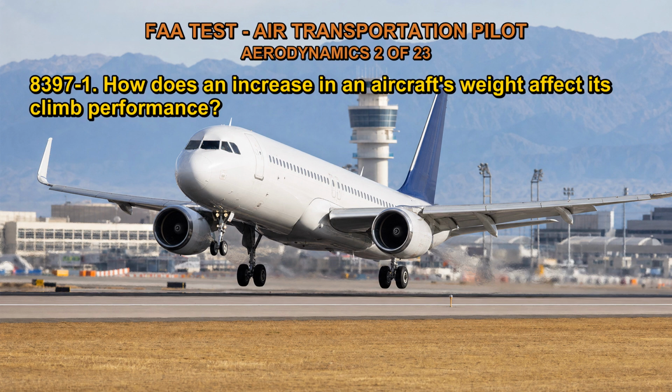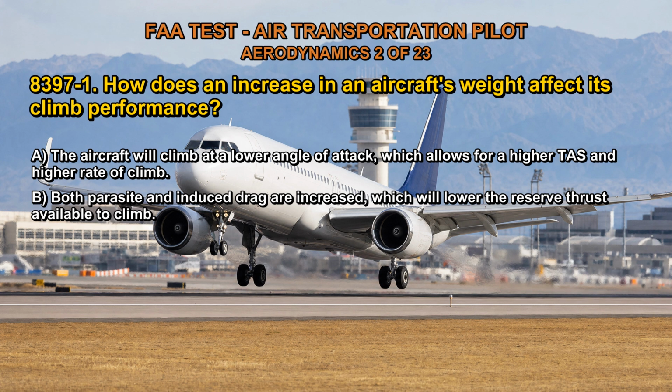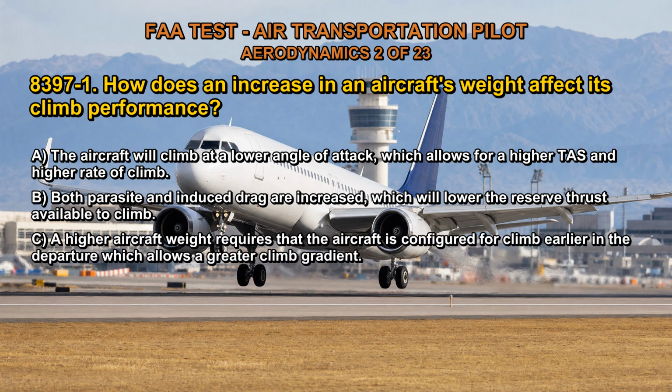8397-1. How does an increase in an aircraft's weight affect its climb performance? A. The aircraft will climb at a lower angle of attack, which allows for a higher TAS and higher rate of climb. B. Both parasite and induced drag are increased, which will lower the reserve thrust available to climb. C. A higher aircraft weight requires that the aircraft is configured for climb earlier in the departure, which allows a greater climb gradient.